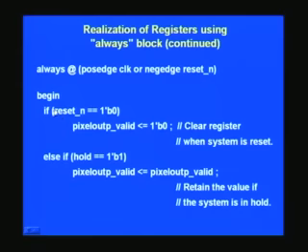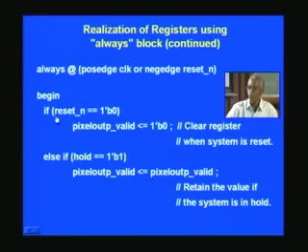So, only by experience you get this. So, do not try to add more than these statements. If you are still forced to add these statements, what you do is you combine this outside the always block and then restrict this once again to 4 or 5, right. Smaller the number, better it is, higher the speed of operation that you get.